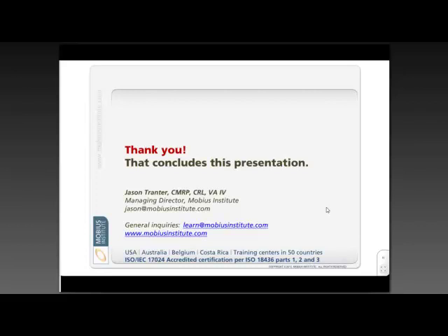A lot of people think that the measurement frequency has to do with the criticality of the equipment. From a pure vibration analysis point of view, the criticality is not an issue. It's the failure modes. We have to take measurements frequently enough to detect that it is failing and so that we have time to do something about it. Criticality is what you use to justify the expense of the monitoring.